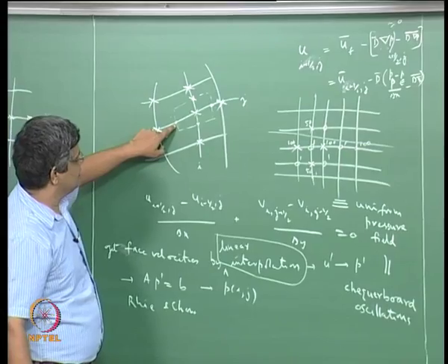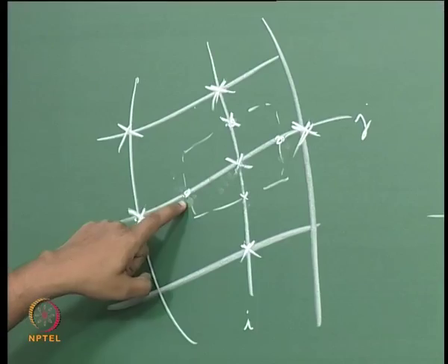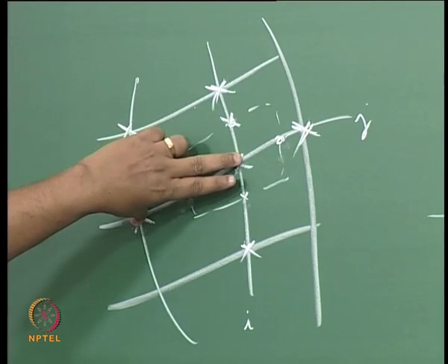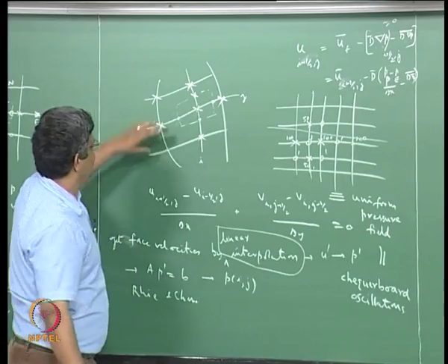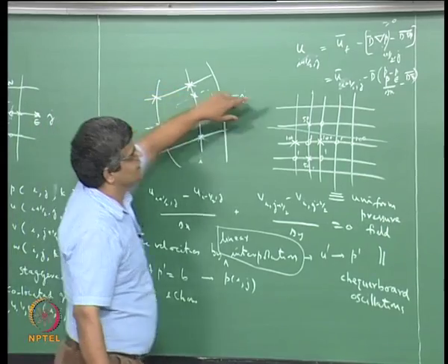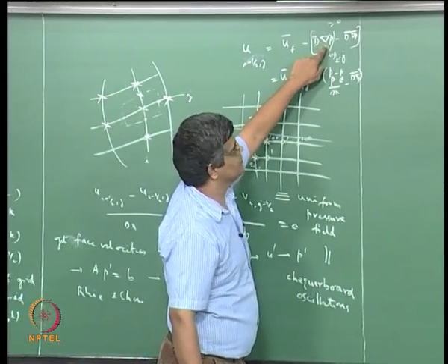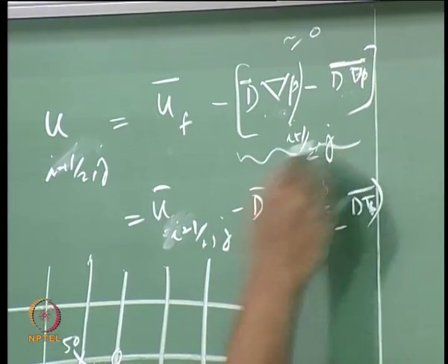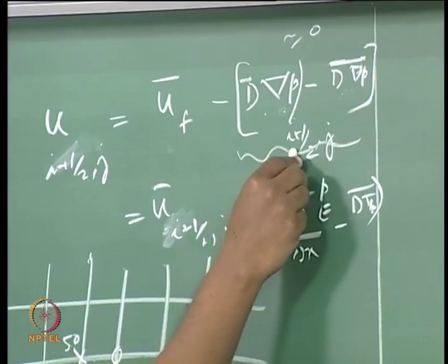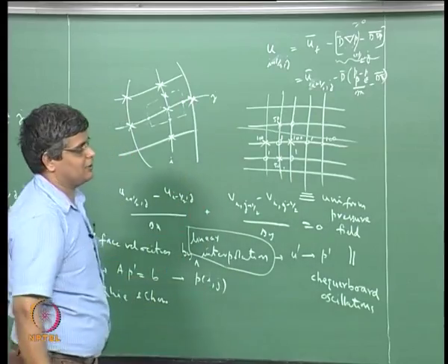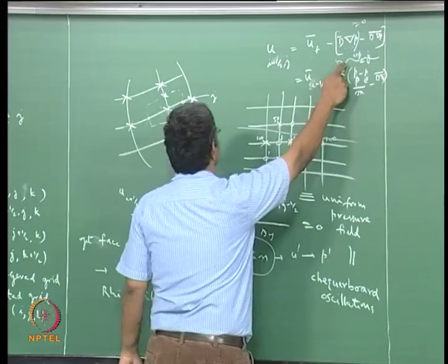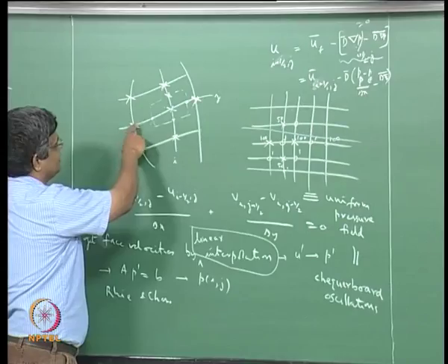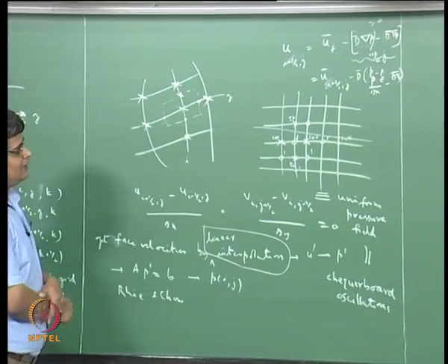So they made this phase velocity determination sensitive to the pressure gradient between 2 successive points, and that sensitivity is introduced into this term here, and the correction that is coming out here will be almost equal to 0 when you have a smooth variation of pressure, but this will be the dominant contributing factor to making this uniform in the case of a strongly varying pressure field.